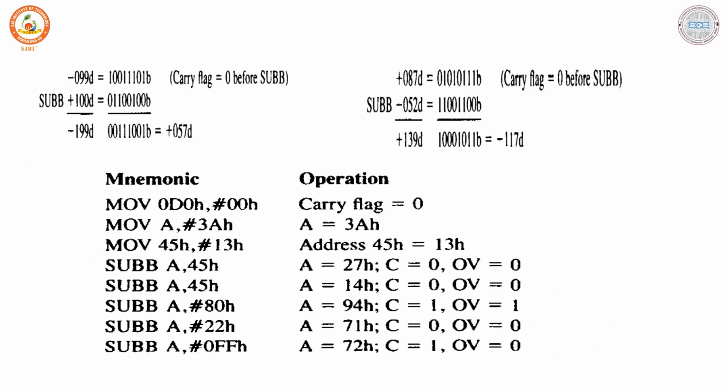So we can also perform signed and unsigned subtraction, for which we are showing a small example. And we know that for signed or unsigned subtraction, especially for signed subtraction, we make use of the most significant bit as the sign indication. And for unsigned, we don't require any such things. Here, as I told you, the high MSB is mentioned for the sign indication. The remaining bits will be taken for performing the subtraction operation, and some examples are shown here. You can just go through it.